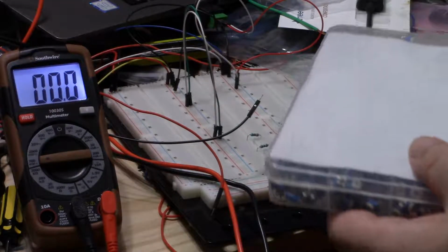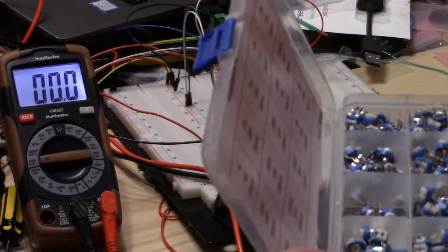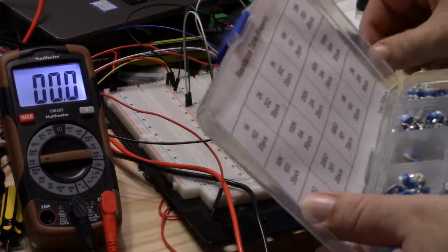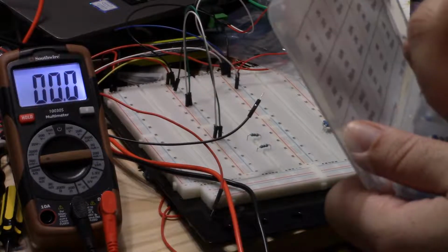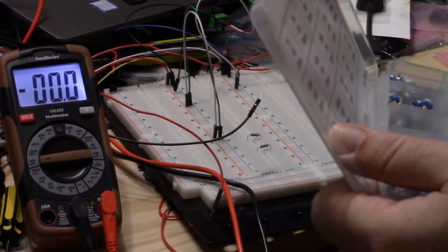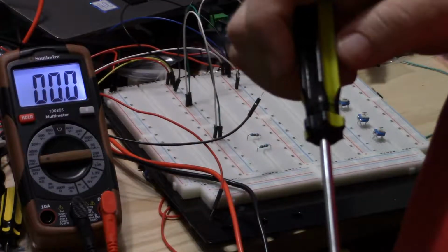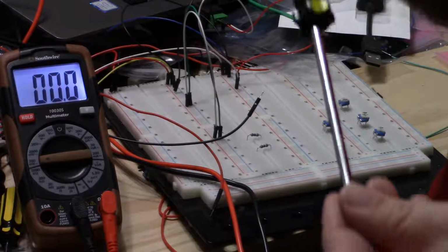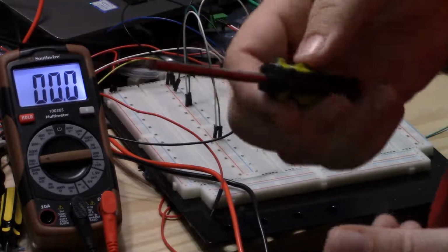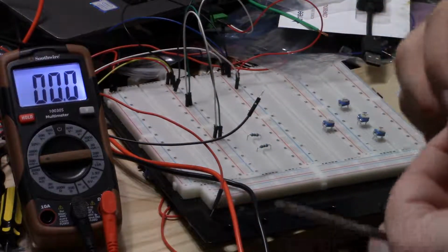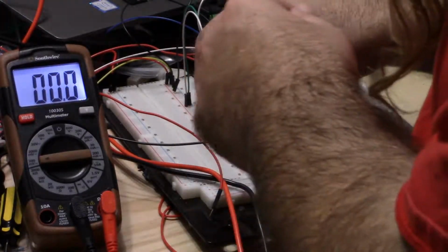The reason I'm doing a potentiometer is I want to try and turn that load down as much as possible. So which one do I have here? 502 is 5K. That seems a bit much, considering my headphones measured at 30 some. So I'm going to use just a 100 ohm potentiometer. I've decided this is safe because I've measured my headphones. They're very low impedance, comparatively. But to be even safer, I'm going to make sure that this potentiometer is turned up to 100 before using it. I don't want to accidentally short something because this is an expensive laptop.